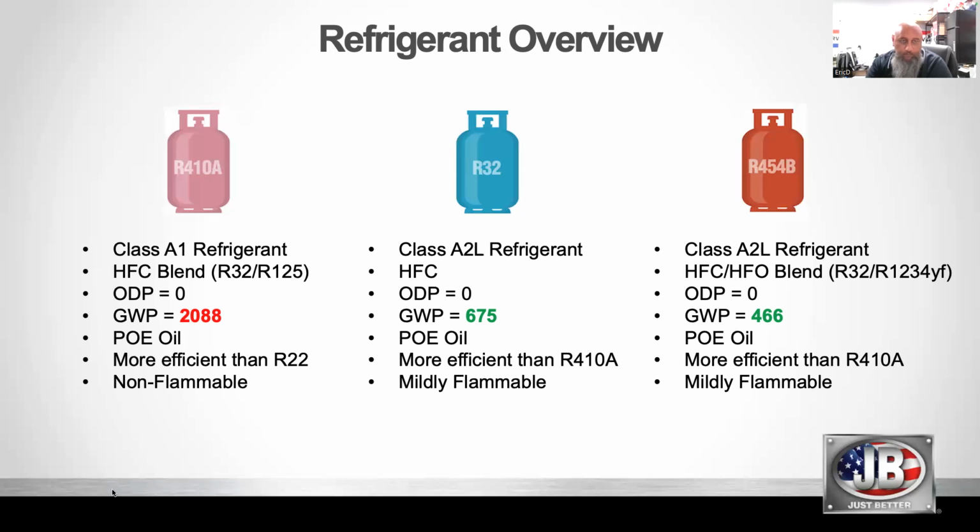Those two refrigerants are pretty much the same in terms of their flammability. And by flammability, we normally talk about the propagation of the flame, compared to propane being highly flammable, something where the flame really propagates. And these are mildly flammable. When I say mildly flammable, I mean mildly flammable. I've heard some refrigerant manufacturers actually compare the flammability of R32 or R454B to olive oil. I think that's kind of understating it a little bit, but that's kind of what we're talking about.